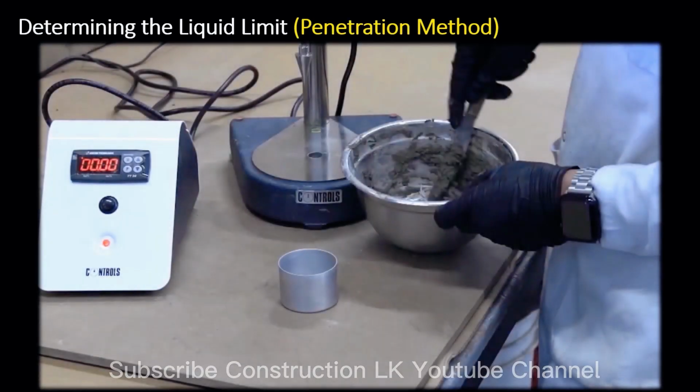Now let's see how the liquid limit is determined using the penetration method. The apparatus for the liquid limit test in this method consists of a penetrometer fitted with a 30 degrees cone of stainless steel. The cone and the sliding shaft to which it is attached have a mass of 80 grams.